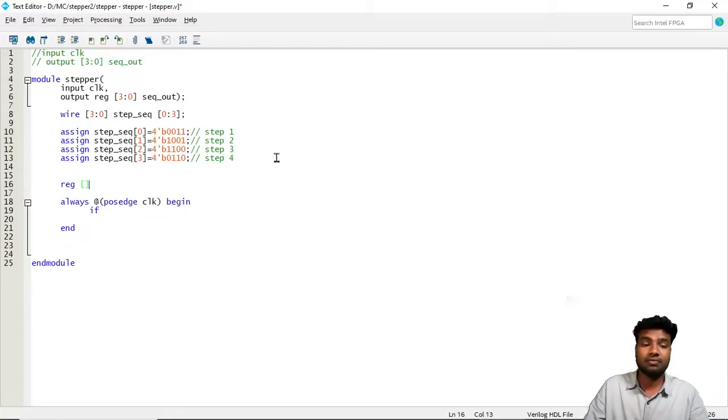First I have to register for the counter. The counter will count from 0 up. Why? As we saw in the last class, our FPGA board has a 50 MHz clock, so it will count up to 5 crore times in 1 second. For that counting purpose, we have to give that much bit range, like 27 bits. So 2 power 27, you can calculate, that much value it will count.